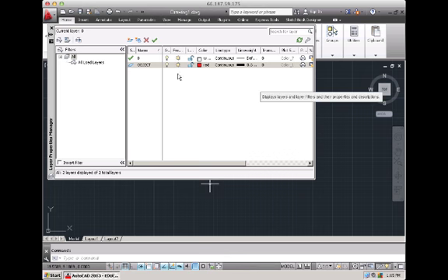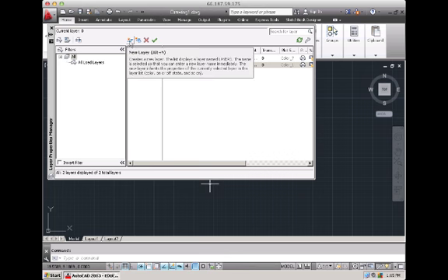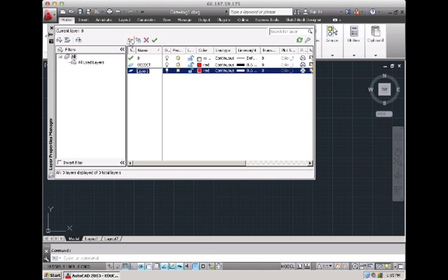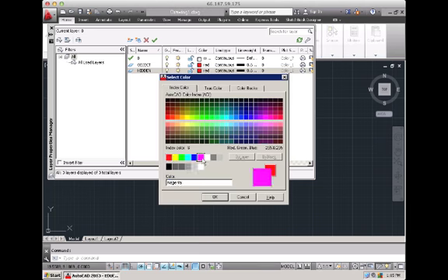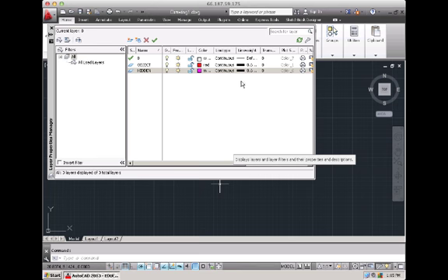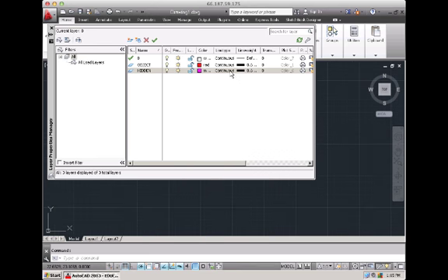Okay, we also have a hidden line as one of the layers. So we're going to click the sheet of paper looking icon again, which brings up layer 1. We're going to rename this one to hidden line. This layer, the required color would be magenta. Okay, but except for the hidden line, on the line type, it calls for a hidden line.